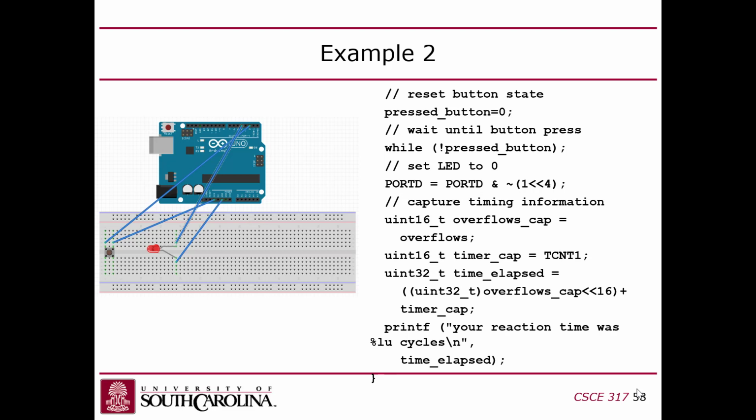After it does that, it'll initialize push button to 0, and then it'll wait for the push button to go to 1. And I might say, well, that's never going to happen. It will, because this is a global variable that'll get set to 1 in the interrupt handler for the button, right? So even though I'd be stuck in this while loop, the processor will escape from that while loop to respond to the interrupt request, because I have an interrupt handler for that. And that press button is a global variable, and you can just keep polling that,